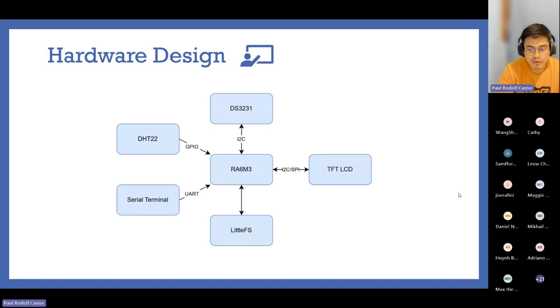The aim is to help the firmware developer understand what peripherals need to be initialized, what drivers to write, etc. Usually, to simplify things, we create a block diagram to show the system, but hardware schematics will also do, although they have much visual noise: passive components, crystals, analog circuits, resistors, capacitors, transistors.